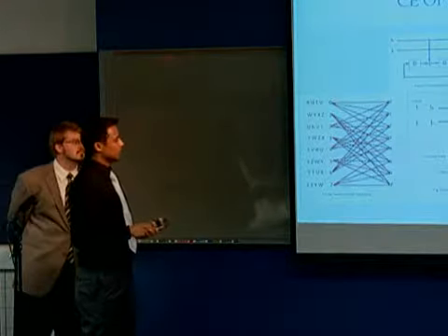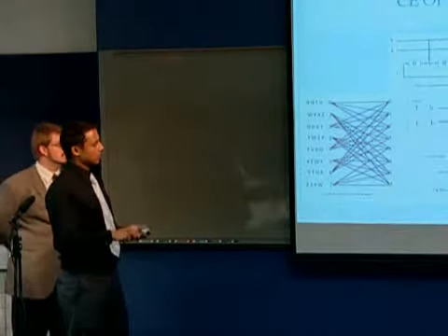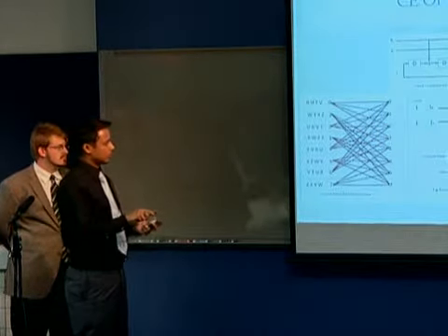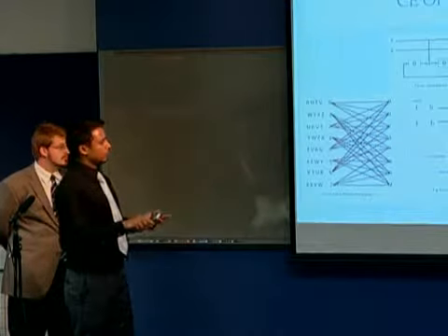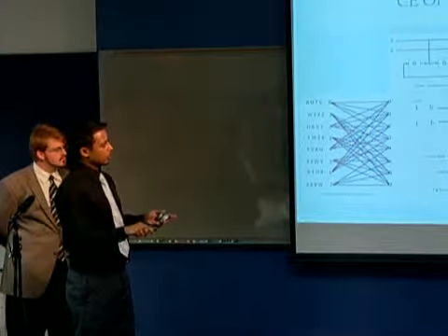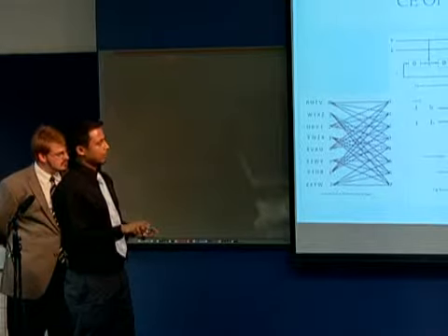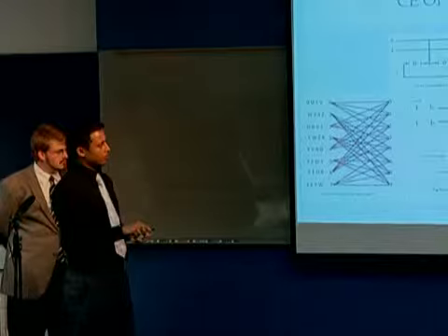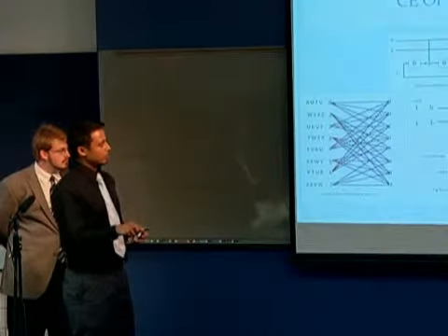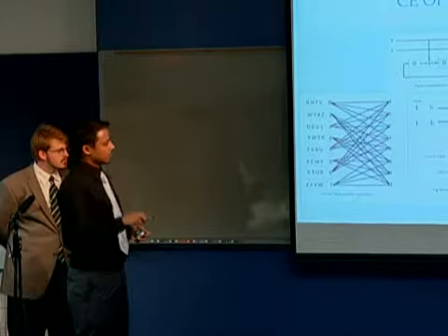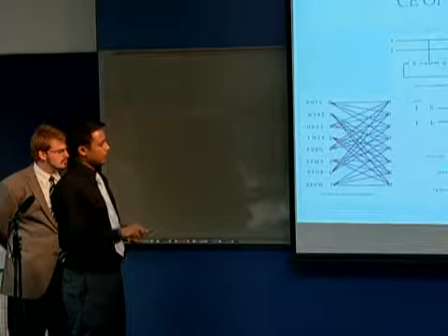Again, the way it works is, say the current state is 0, 1, 1, that is 3, and the input is 3. The output would be 1, 1, and the last output bit would be the same as the current state of this flip-flop, so it's going to be 1, 1, 1. So the output is 3, which refers to the Y subset. The next state is again determined by this feedback loop.